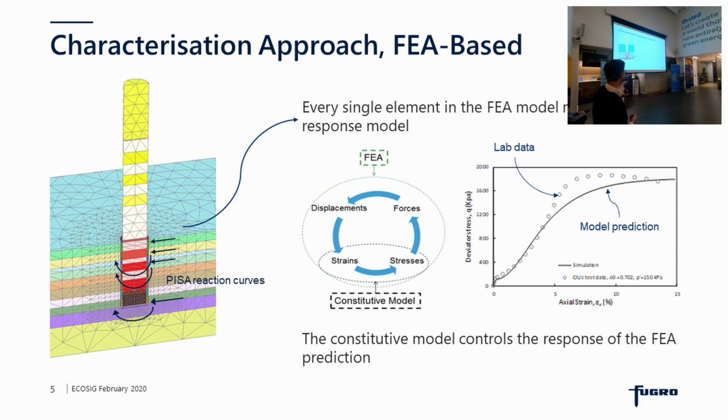So we've got our PY curve response. We're also looking at our moment or distributed moment response and what happens at the base of the pile. So a lot more aspects to this design approach, and Harvey later will tell you a lot more detail about that approach, which hopefully then makes sense with what I'm telling you here. But essentially, every single element in this mesh or this representation of our foundation needs a response model.